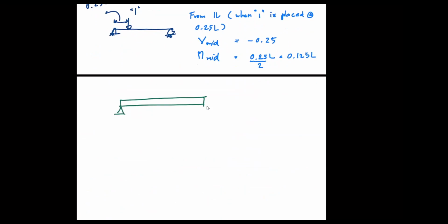This is my hinge, that's my roller, and that's my reaction. Let's say if this is my RA and I want to allow it to move without restraint, what do I do? That would say simply that RA would need to be able to move up and down, right? That is the meaning of move freely without restraint.